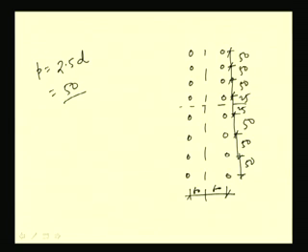So, the largest amount of load will be exerted on the outermost rivet, either here or here, because from the last class we have seen why it will be the largest: the FA will be downward and this Fn will be at 90 degrees with this radius, and for other rivets it will be less.